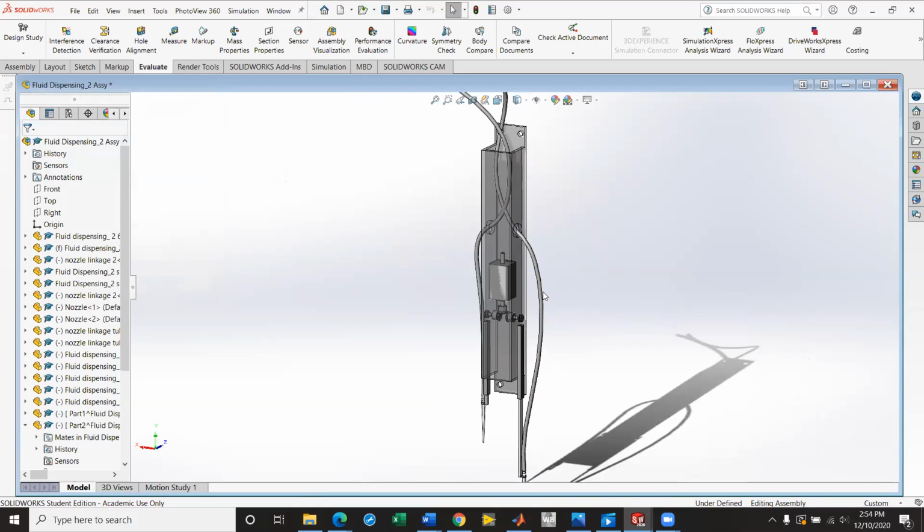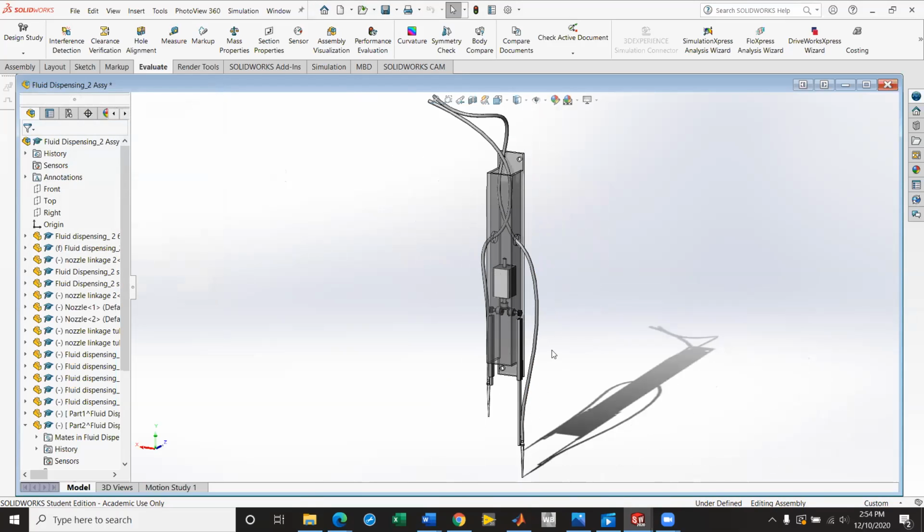My big concern would be trying to get the motor in the right location. Typically your motor has a flange on the front of it that you're mounting with. So you're going to have to either mount the motor onto the flange and then stick it all the way down inside and somehow get that perfectly aligned. So it might be easier to design it like a clamshell system, so you can get inside of there versus trying to fidget and get the screws through the tube.